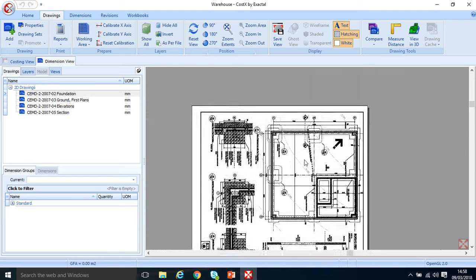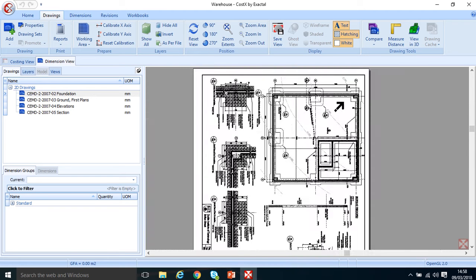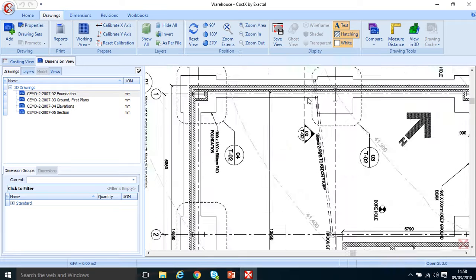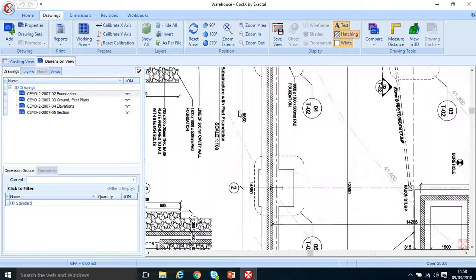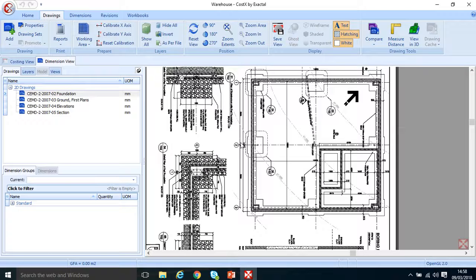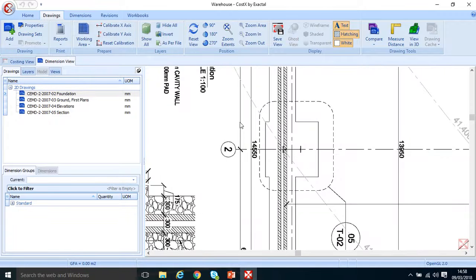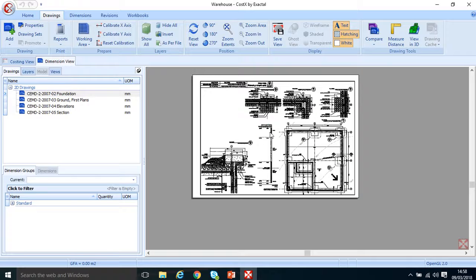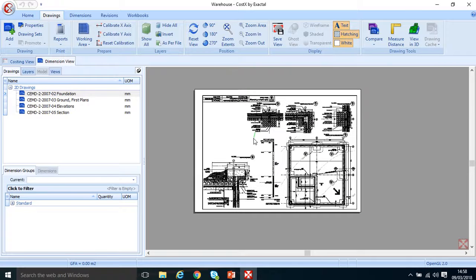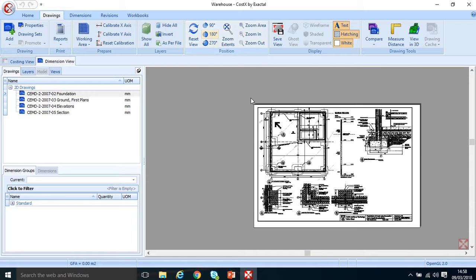Again, the first thing I'm going to do here is rotate that drawing. I can do it a few different ways. I can right click on a line I want to rotate. So in the bottom of the drawing I want this line to essentially be my line. So I'll hover over it, right click, rotate to selected line. And again that has turned the drawing 90 degrees, but I want my tiling down on the bottom right, so I may adjust that by turning 180.